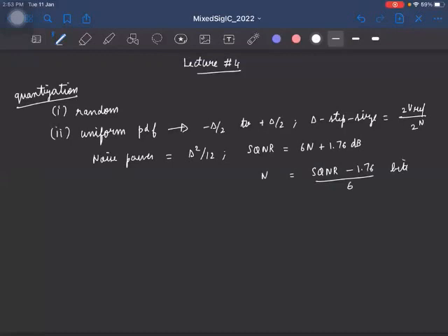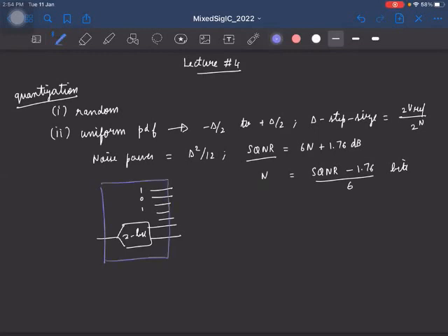Okay. Now let's see how to measure this SQNR in practice. We need to measure this SQNR because in practice, this is how we will characterize the ADC to find how many bits the ADC can actually resolve the input. Because what I can do is take a 2-bit ADC, right? So it will have just 2 digital outputs. I can randomly add 8 lines and connect them randomly to ones and zeros, put it in a black box, tell you that this is a 10-bit ADC and sell it to you, right?